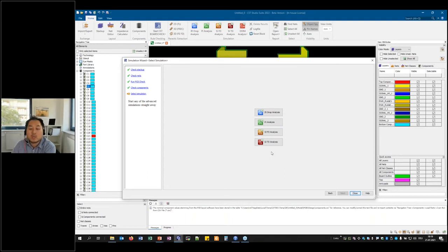Here you can start the analysis for your interconnect interfaces, where you can see the waveform later on. You can see the overshoot and undershoot of your signals. You can see the delay, and then you can wrap this time signal and see it as an eye diagram.